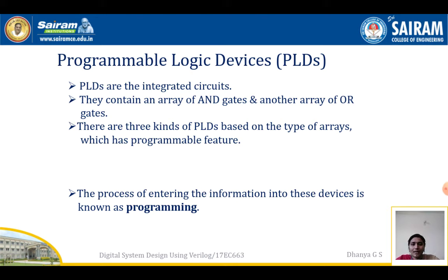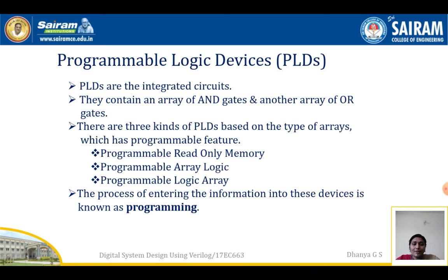They are integrated circuits. They contain an array of AND gates and another array of OR gates. There are three kinds of PLDs, based on the type of arrays which have programmable features. One is programmable read-only memory, next is programmable array logic, and the third one is programmable logic array. We'll study programmable array logic in our syllabus.